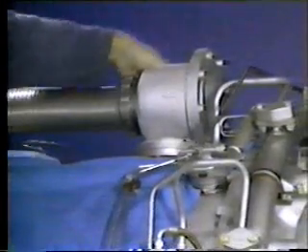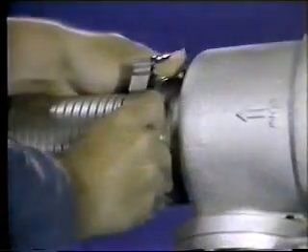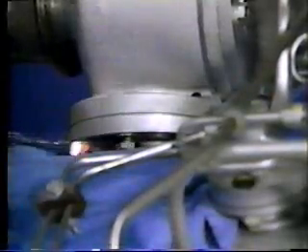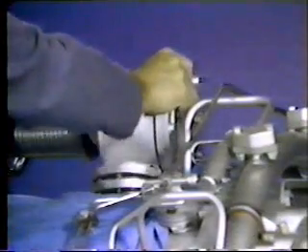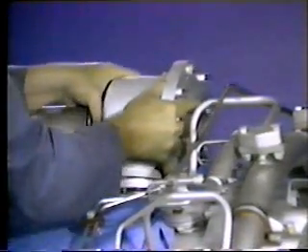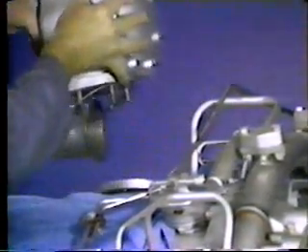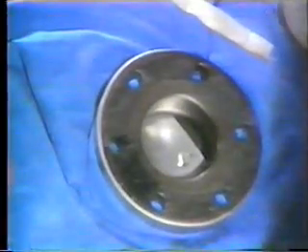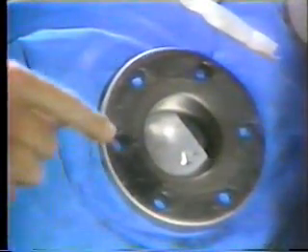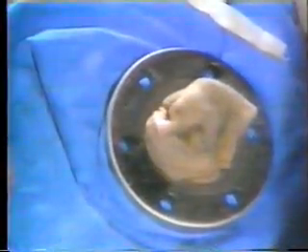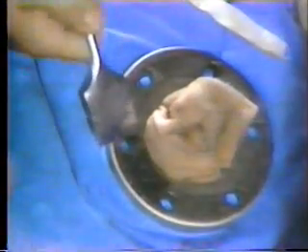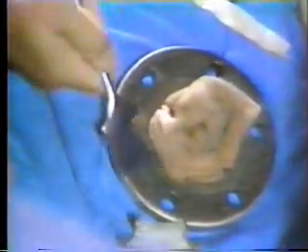Remove the V-band clamp from the bleed air duct. Next, remove the 6 retaining nuts and washers. The valve can now be lifted from its mounting flange. Some rocking motion may be needed to break the gasket seal. Portions of the gasket may stick to the flange and need to be scraped away. Plug the hole with a cloth to prevent debris from falling into the combustor. Remove and discard the gasket seal.